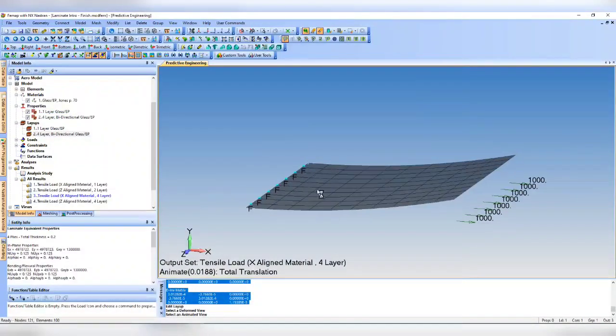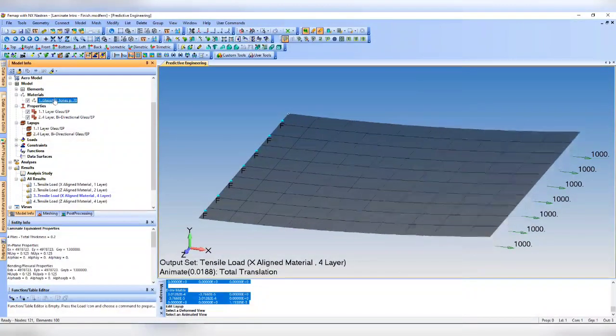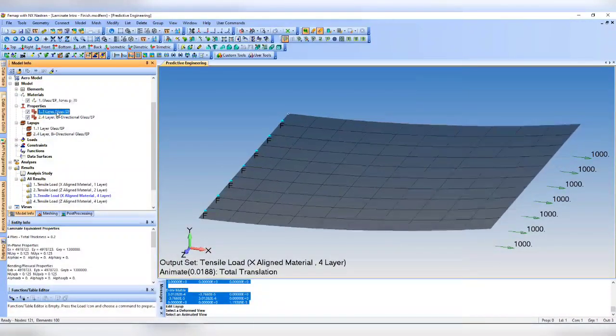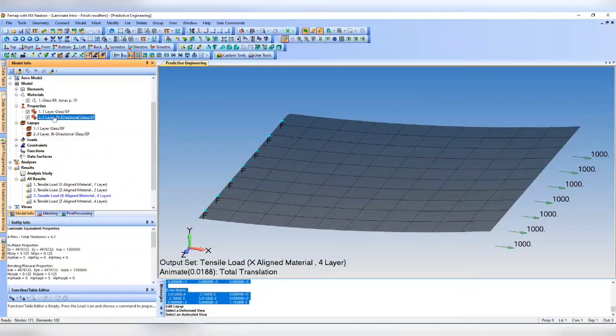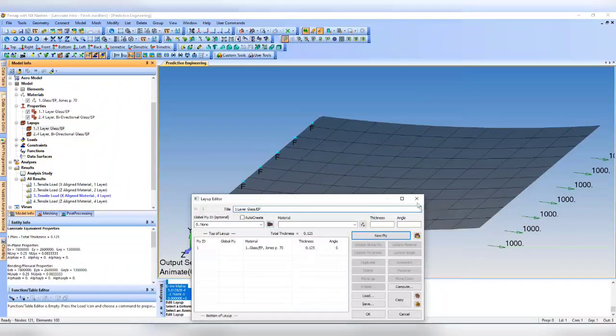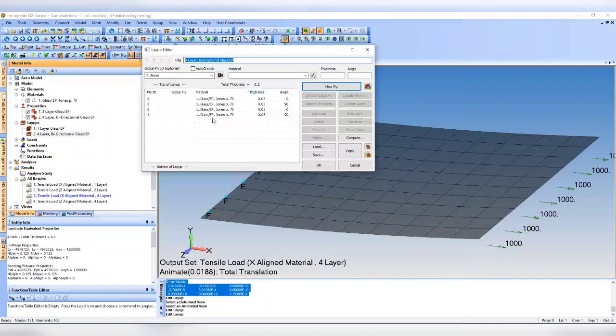The main intent of this tutorial is just to go over the material properties of composites, the lamina. You need to create a property for your composite laminate, and in your laminate, you need to define a layup, whether it's one ply, which is typically never the case. You're going to have more than one ply, so this is typically the case.